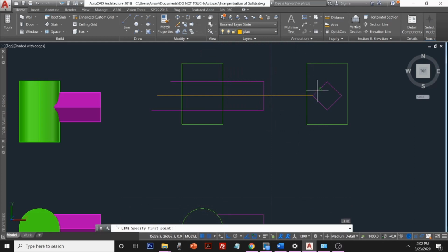And using some lines, let us now project to show where the lowest point would line up with. If you draw across, you realize that it's the same thing as right here, same thing as that point there. And the top here will line up right back to this point here, so that's the same thing. So what we have now is highest point, midpoint, lowest point. On the 3D version, highest point, lowest point, midpoint. But how do we identify the midpoint? Notice that the midpoint is not vertically aligned with the highest and the lowest point. It's a bit further back.